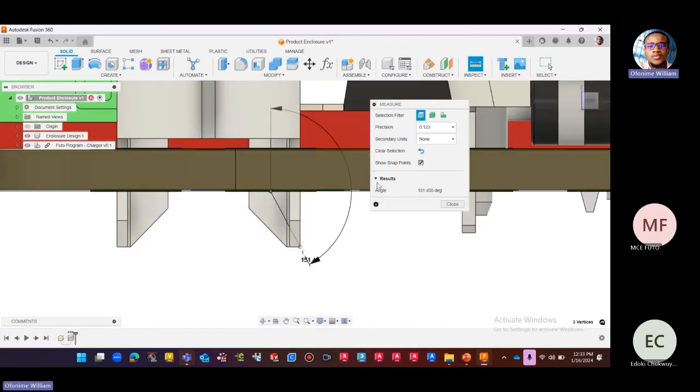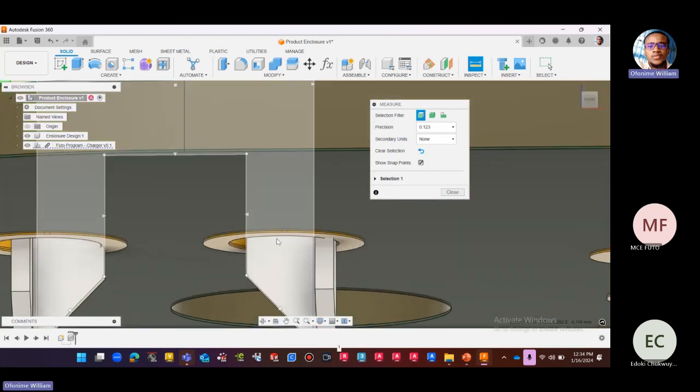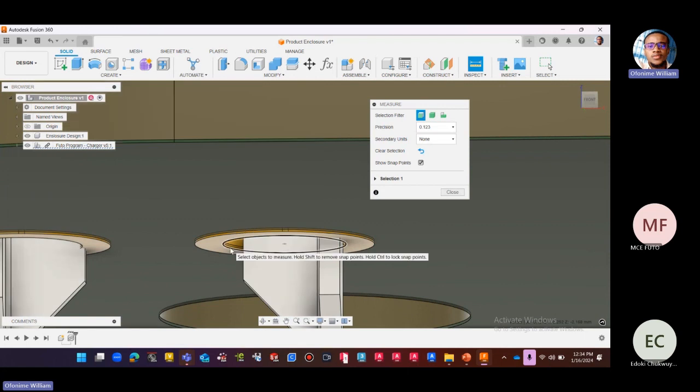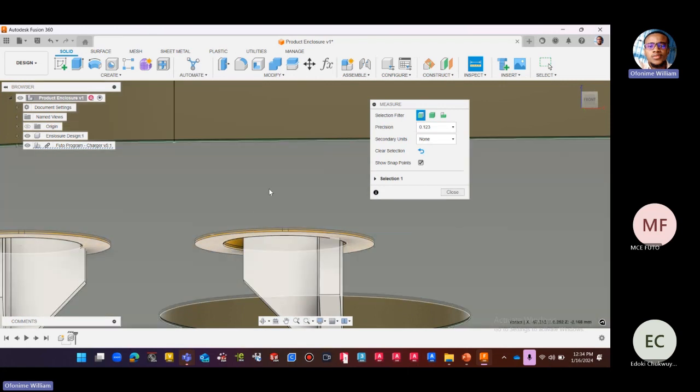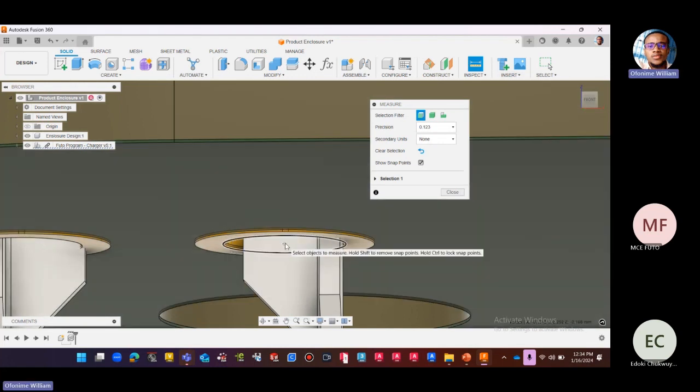Right? Take that again just for the purpose of clarity. I said click on the first point here. Then I moved in. I wanted to take the one in the middle, but when I move to the circle, it shows, and if I move away, it's off. So I will hold Control, right? I will hold Control and move in. The control allows that center point to be snapped and held. I can move in and then take that measurement.